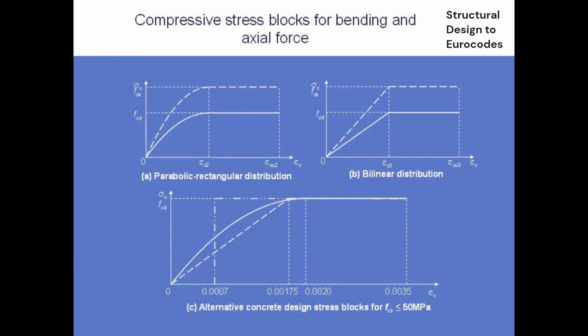Just before I say something quickly about that stress distribution, the other thing is that there are no formulae given for bending in the Eurocodes. So we'll talk about that. There is a formula presented on one of these slides, but it doesn't give you any formulae. So really you are quite dependent on using software or simple formulae that somebody else has given to you. I recommend using the computer, to be honest with you.